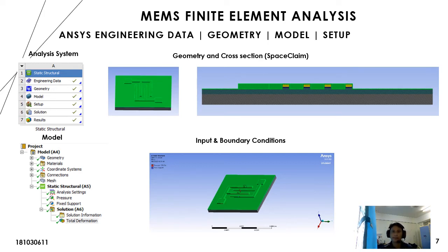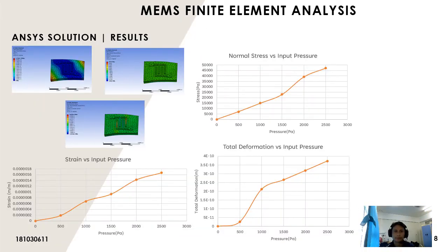Pressure is given in the middle of the body surface. The body material sustains that pressure through deformation, which causes stress in the material, and the entire model comes to a state of equilibrium for a static structural model. Next, we get the output of the simulation result of total deformation, minimum and maximum strain, and minimum and maximum stress. Total deformation is a deformation option that allows you to examine all of the model deformation results in 3 dimensions, which are X, Y, and Z.